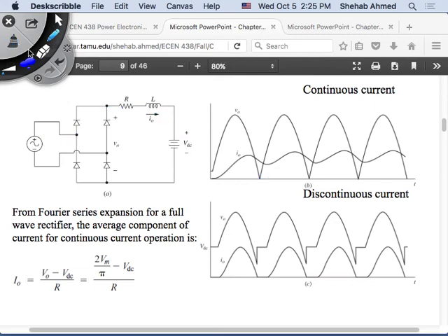Okay. Let's agree on something, right? If that's passive sign convention, you agree with passive sign convention? If this is my source and current is coming into it, I'm charging it. If this is my source and current is coming out of it, this way, I'm discharging, right? In this case, can I do this? Current will come out here, which means it will have to go through here, opposing this diode polarity. So I cannot do that. You cannot do that here.